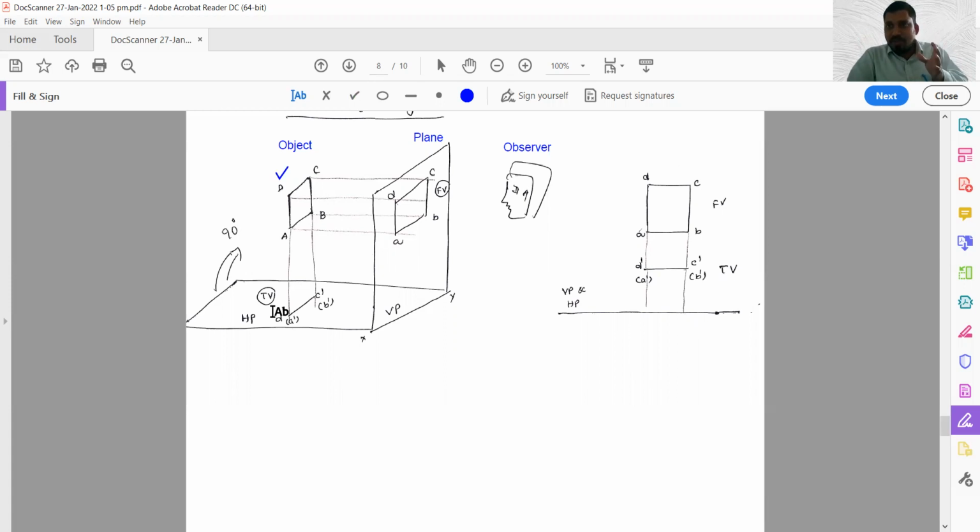In second angle projection, the vertical plane and horizontal plane will come on one side above the reference line, and front view and top view both will be matched. So it is very difficult to understand which one is front view, which one is top view, and sometimes very difficult to identify the dimensions of the object. That's why we don't prefer second angle projection for industries.